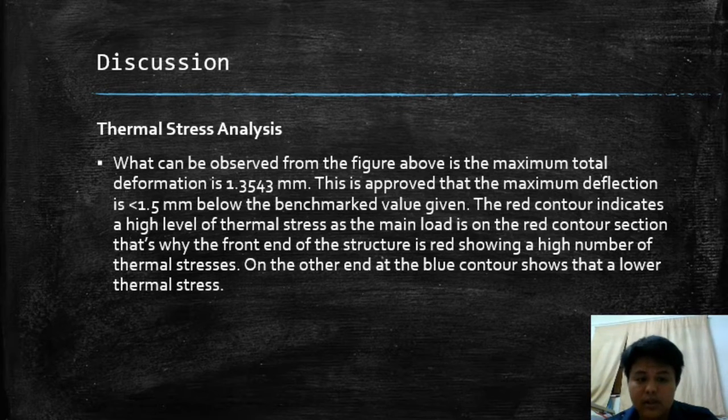Next discussion is the thermal stress analysis. What can be observed from the figure is the maximum total deformation is 1.3543 mm. This is a proof that the maximum deflection is below 1.5 mm, the benchmark value given.